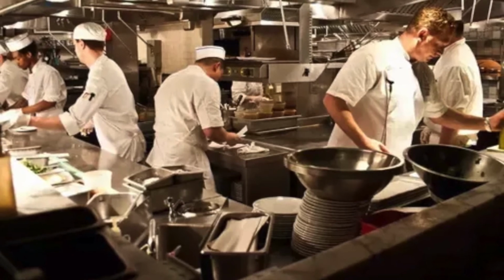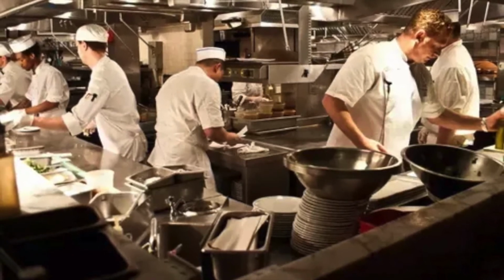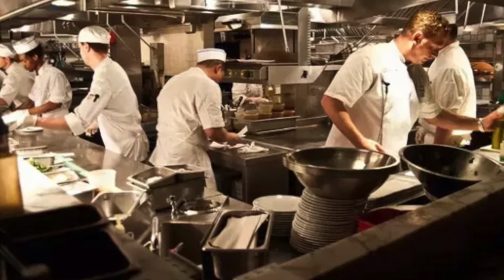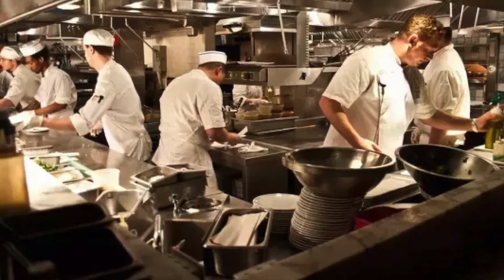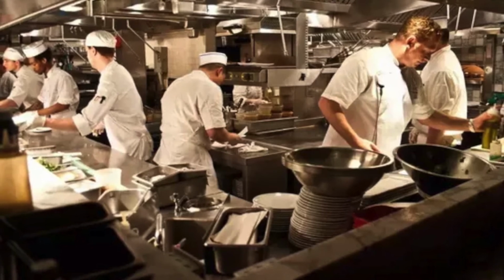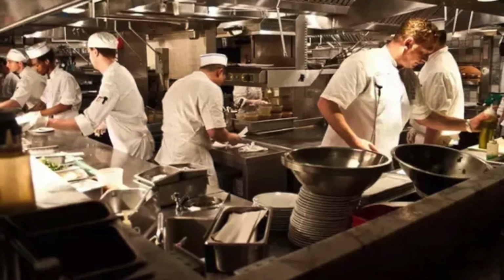Some possible causes for this may be insufficient cooling in the kitchen, so the kitchen gets hot during cooking. Or maybe the room temp sensor is mounted in a poor location, like on the ceiling or near a piece of equipment where it's going to read hot.